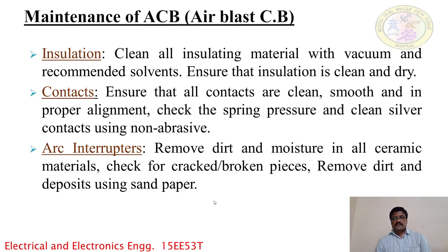So as a result, the moisture is deposited. Remove the moisture, and some unwanted broken pieces that are deposited within the plates or contacts. So remove this also and maintain it by using the sandpaper.